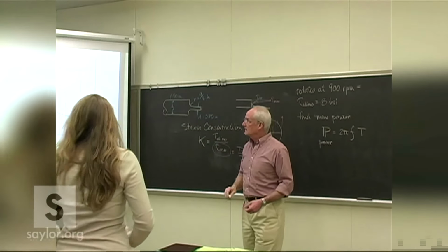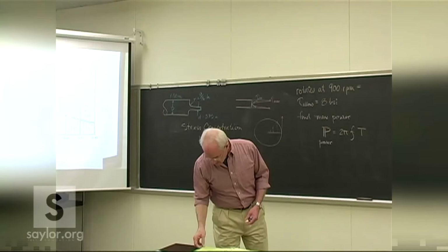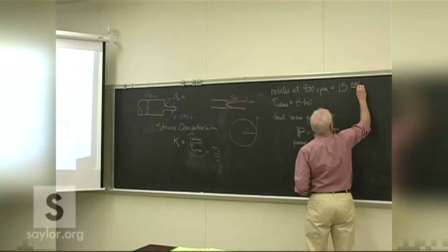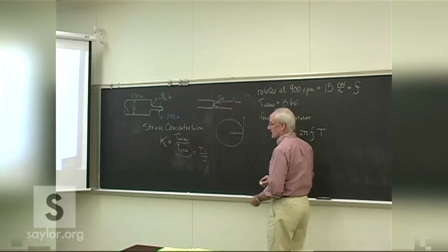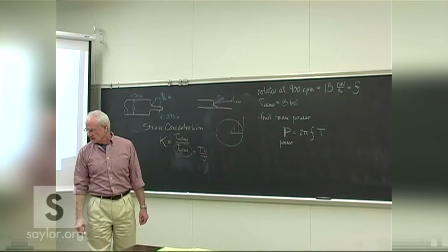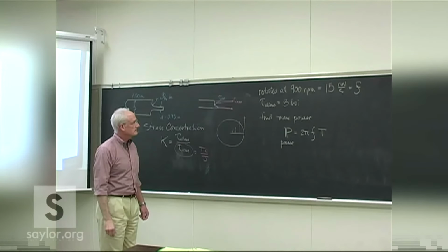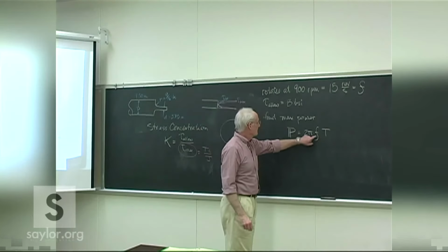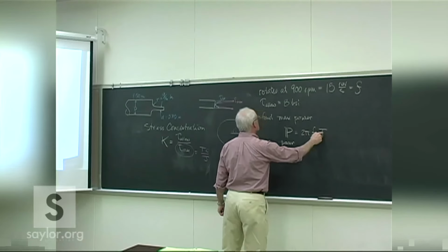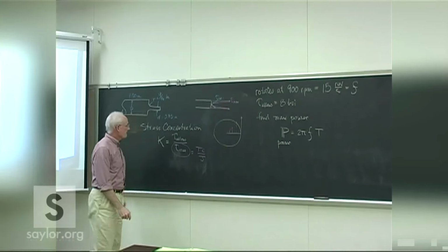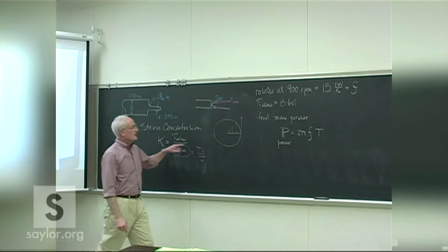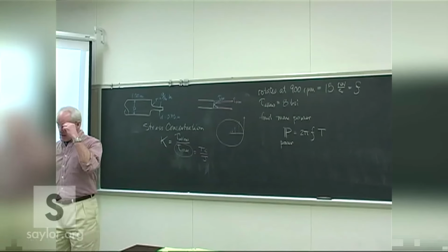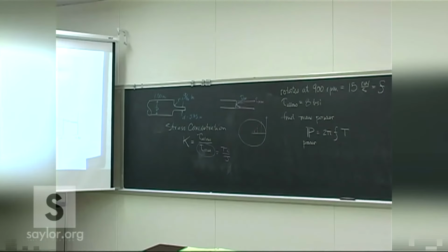All right, so just to help you a little bit, whether you can do it. So that's the engineering frequency, the revolutions per second, or hertz, if you will. And that's the number we use in here. So we need to find a maximum torsion from the allowable. Once we find that, then we can calculate the maximum allowable power. Any power load over that is going to overstress the shaft.